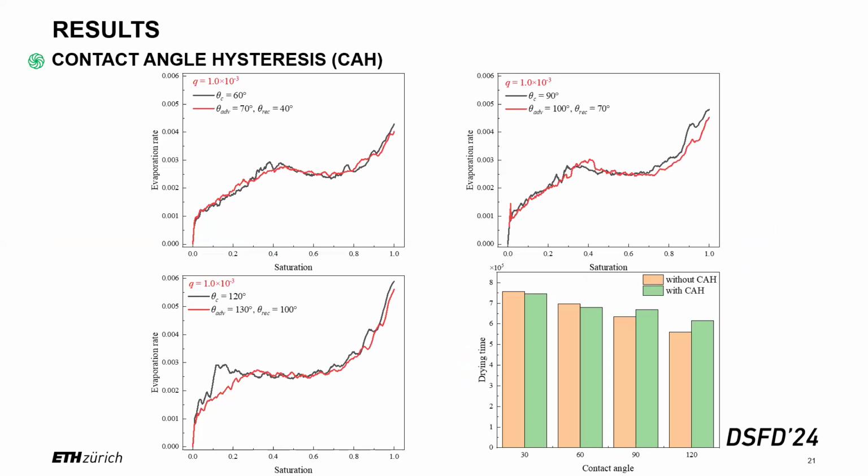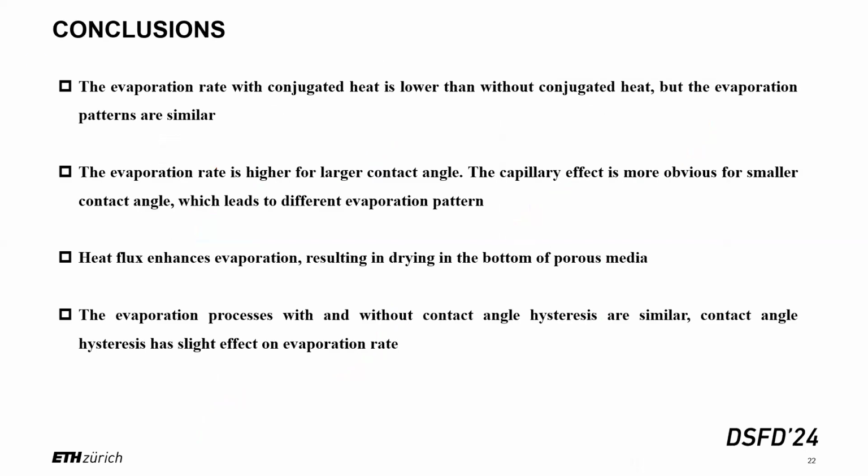But for the hydrophilic surface, the contact angle hysteresis increases the evaporation rate. I think this may be caused by the smaller contact angle, which increases the liquid-vapor interface area. And the last section is the conclusions.